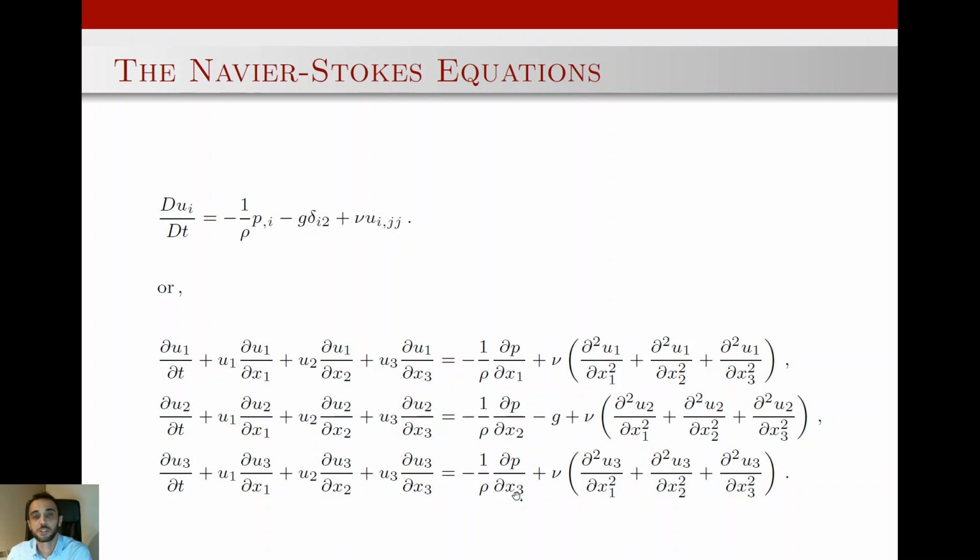We can rearrange the terms, and then this is the equation that we find from the conservation of momentum, or in an expanded version, we can have this equation, which is known as the Navier-Stokes equation. It is a set of partial differential equations that are second order, and they are nonlinear because they have the unknown and its derivative multiplied by each other.